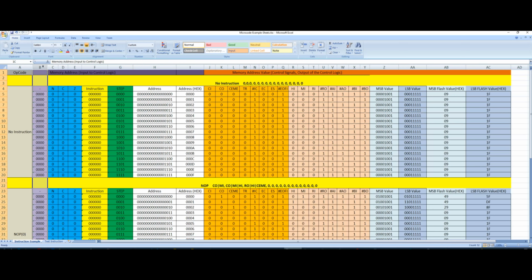Now, if you remember from the circuit, the four most significant bits were all set to 0. In fact, in the circuit, we tied them all to ground. That's why we have a column here which has 4 bits in it, all of them set to 0. That is followed by our flags, which gives another 3 bits here. And then we have our instruction, which is 6 bits.